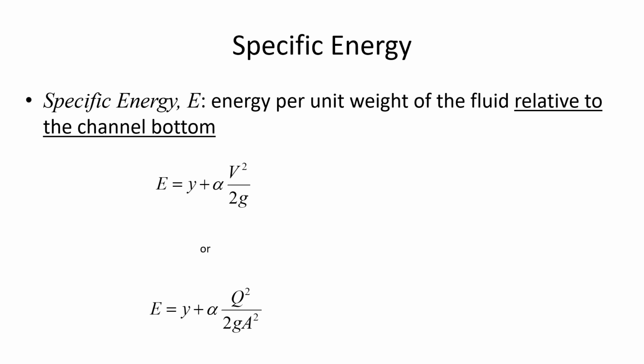Do you remember what Manning's equation predicts? When you solve for y using Manning's equation, what is it assuming about the type of flow that you've got? Uniform flow, that's half of it. That's right. Uniform means that there's no change in flow with respect to position. So Manning's equation assumes uniform flow and what else? Steady flow. Good.